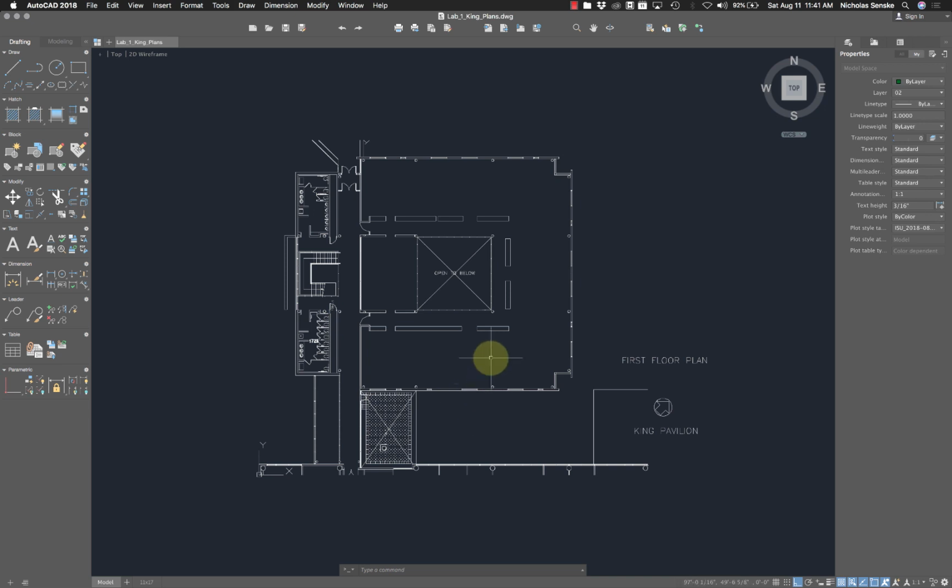The first thing you're going to do, when you've got AutoCAD open, I basically just opened it up from a fresh install. If you're looking at the bottom of the screen, you'll have a lot of stuff activated. These are your options. I want you to go ahead and unclick a lot of these. Make sure that polar tracking is turned off, dynamic input is turned off. If it's blue, it's turned on, so we're going to turn it off.